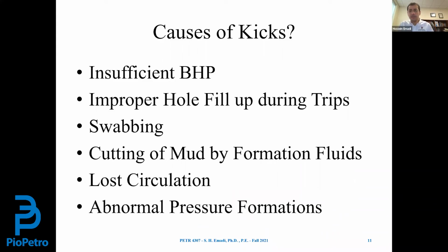The next step is why a kick happens. What are the causes? There are several reasons, but all of them fall under one umbrella: insufficient bottom pressure. Whenever the bottom pressure goes below formation pressure,